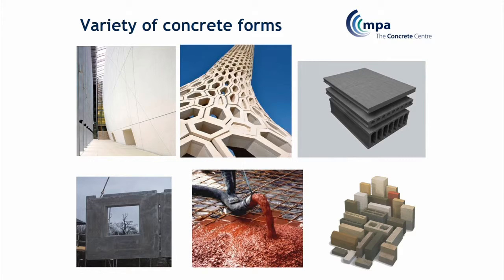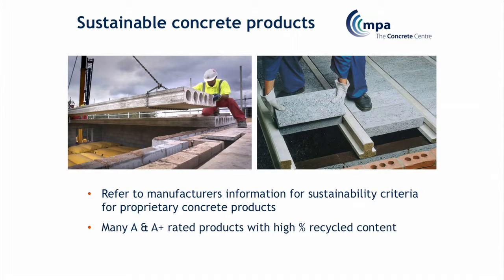Now, there are many different types of concrete, and each of those have very different corresponding embodied factors as well. So the sustainability credentials of your concrete are very much going to depend on where you're getting it from, but also what type of concrete it is. Blockwork, hybrid, precast, coloured, sprayed, all those different things can be very different. If you're buying a product, actually a lot of the information will be provided to you by the manufacturers. There are lots of A and A+ rated products out there, and they've got very high recycled content. All this information will increasingly be made available to you as well.